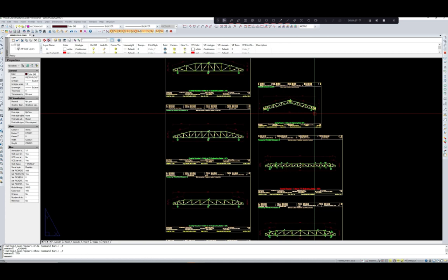Because of the presence of sheathing on both sides of the wall, the load transfer to the base is actually in the form of UDL. You can say at most the reactions at the lower end of the studs, vertical studs, are more or less equal. But structural software analyzing a bare frame will not produce that effect.